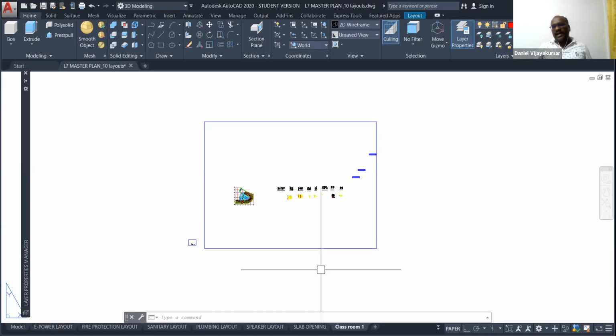Sometimes the engineer will ask you, I want the drawing at 1:100, 1:50. That means when they use the engineering scale, they can choose the 1:50 scale ruler to measure your drawing. Then automatically the drawing will reflect the exact dimensions of that particular line or arc or whatever.